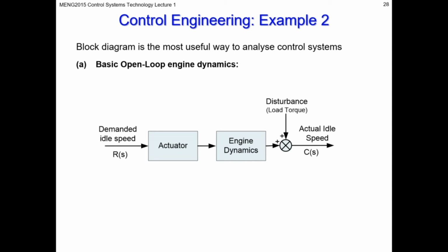on vehicles. The idle speed you demanded would be basically what you want to achieve, so that would be the set point. You'd adjust that with a little screw on the carburetor itself. The actuator would be the carburetor, which allows a certain air to fuel ratio, or let's say charged air with fuel in it, into the engine itself. And that would cause the engine to either accelerate or decelerate as it idles.